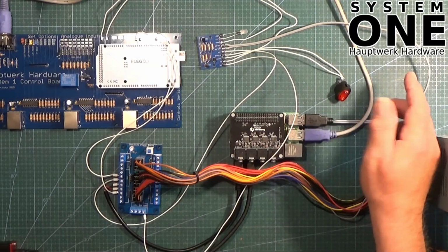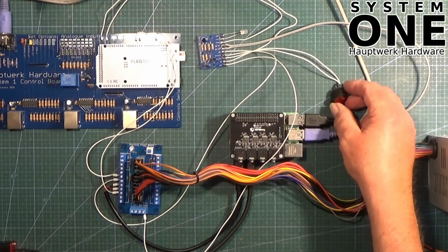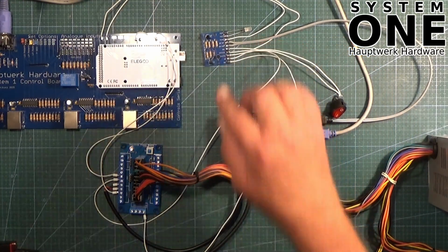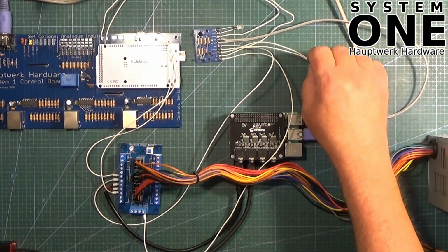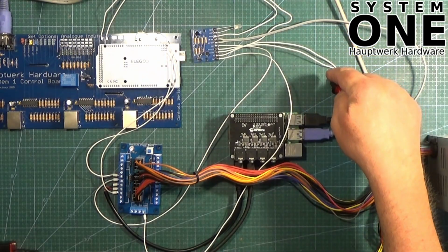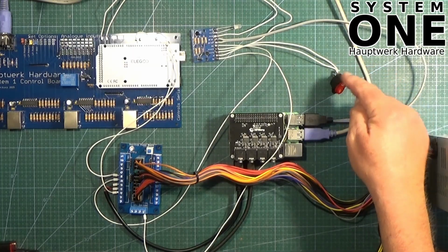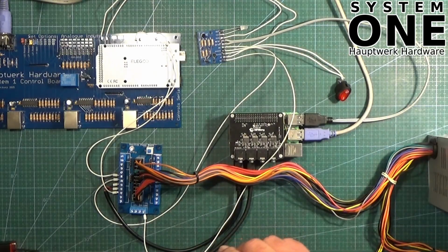Obviously we remove the mains power and all the other connections from the switch, and it ends up with just two wires. It's just an ordinary on-off switch, and they come back to our power management board to the two contacts marked switch. It doesn't matter which way around they go. So that's what that's about. Normally, as I say, that would be on the front of the organ. The LED would be mounted near it. I normally use a little chrome bezel so that it just makes it look nice and neat. So that's what that bit's about.